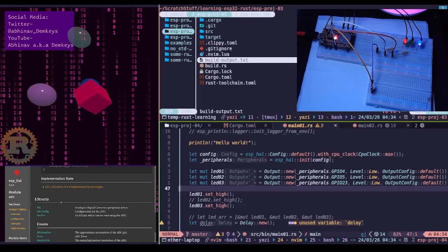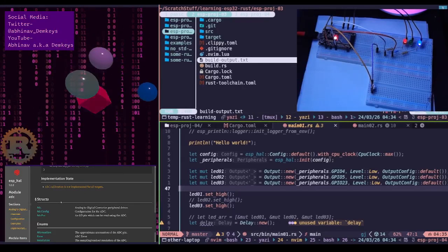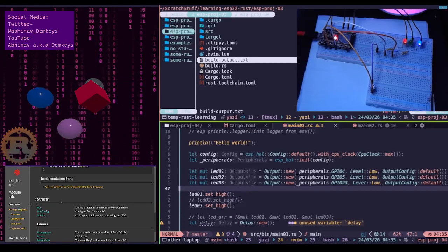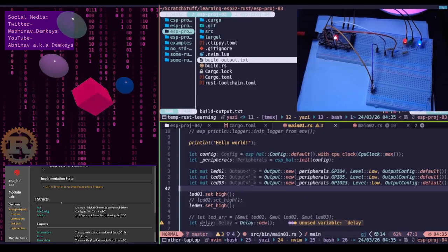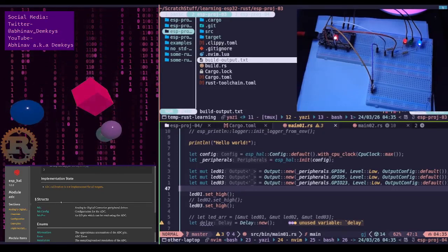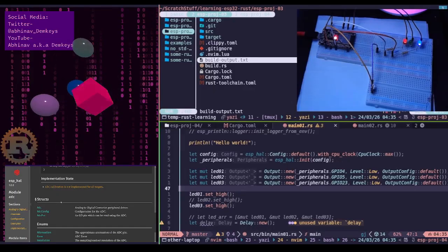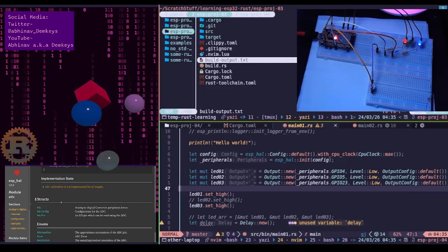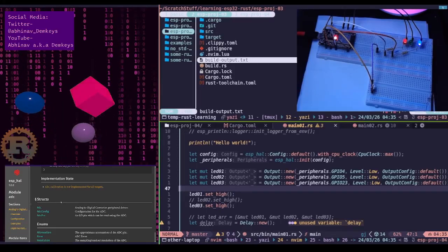Hold on. Let's continue reading. Okay, anywhere in between, you are essentially creating two resistors. R1 is the distance from pin 1 to the wiper. R2 is the distance from wiper to pin 3.